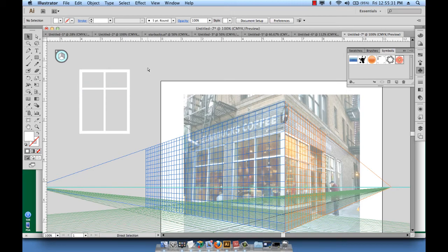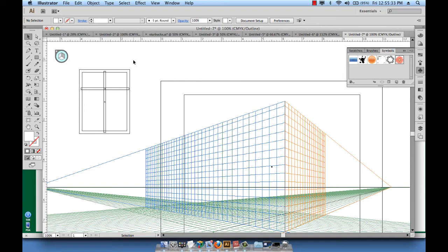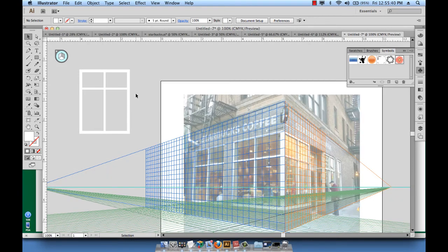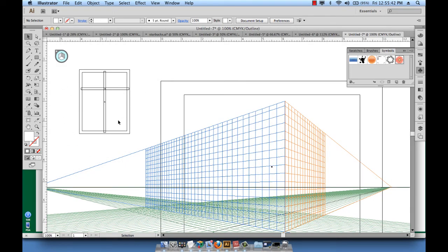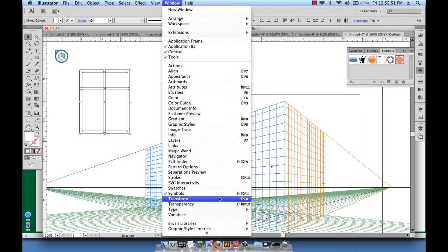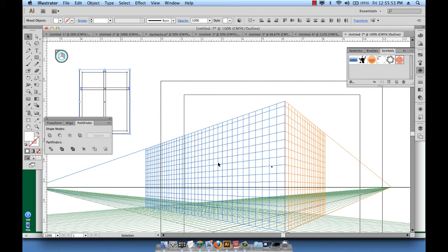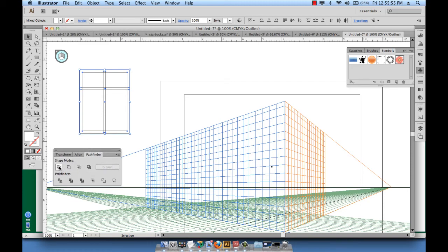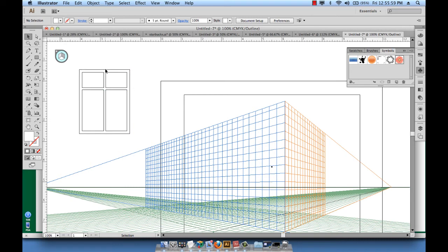Now, again, if we go to outline mode, we can see that we have the frame, a vertical long rectangle, and a long narrow horizontal rectangle. So how about we merge all of these so that they become one element rather than having three elements? So all I need to do is just select them all and then go to, again, the Pathfinder that I shouldn't have closed. It's right here, and then hit Unite. And so my three shapes become one shape because they unite.